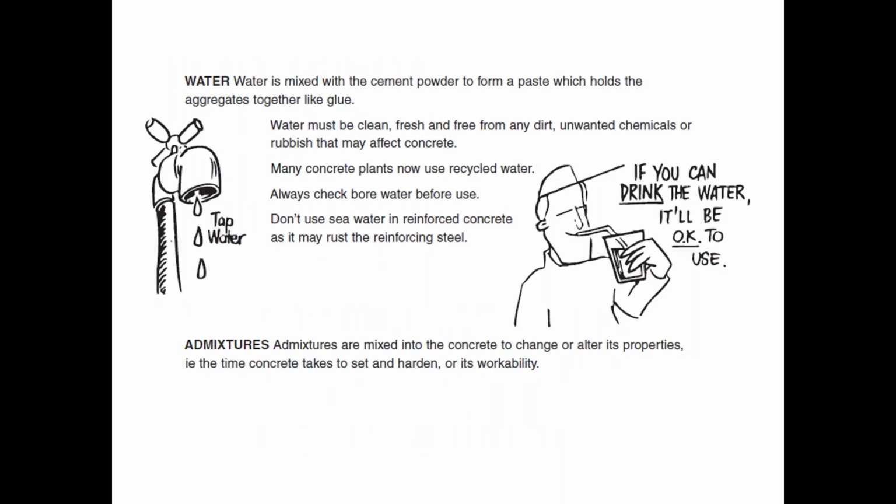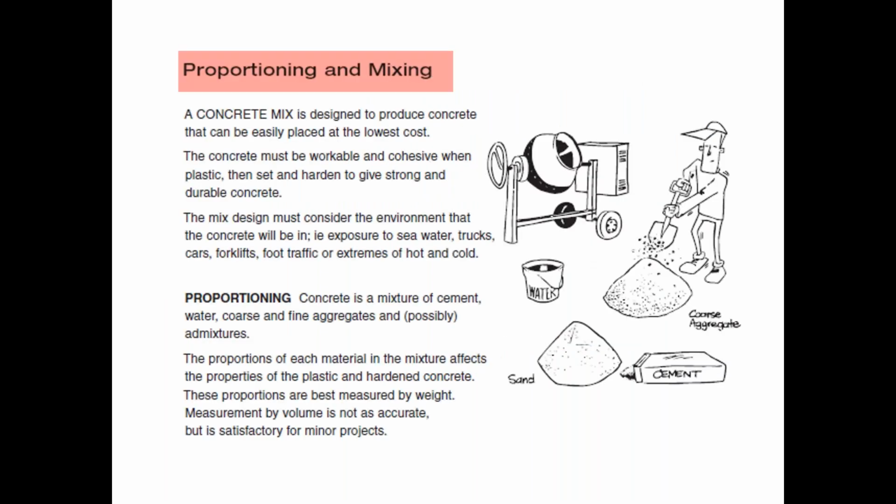Now, the key thing with water is it's pretty simple. If you can drink it, you can use it for concrete. And that's an adage that's been used in the concrete industry for many, many years. What it's trying to say is don't use seawater or salt water for concrete. It causes degradation and especially corrosion of your reinforcing steel, etc. That's about it with water. It's not highly complicated on that.